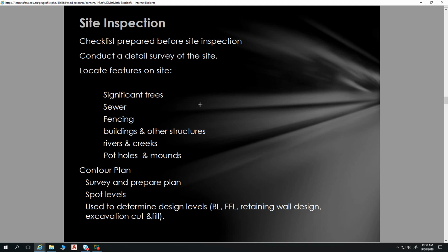We've got buildings and other structures, but certainly neighbouring buildings as well. I'd check access to the site, road access, and all your services. Whether it's a busy road. It's probably important to have established your zoning and your zoning constraints before visiting a site as well. But then there might be a bunch of other site-specific things to think about. And a lot of this research can be done prior to going. There's so much research that can be done prior to going to a site.